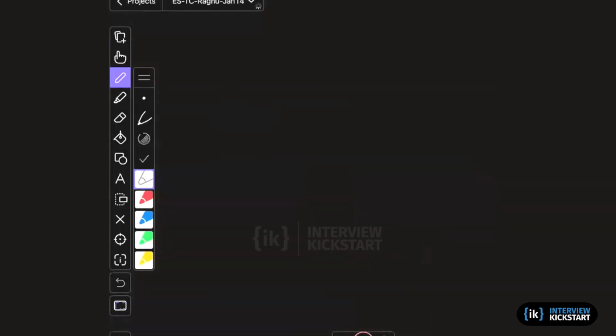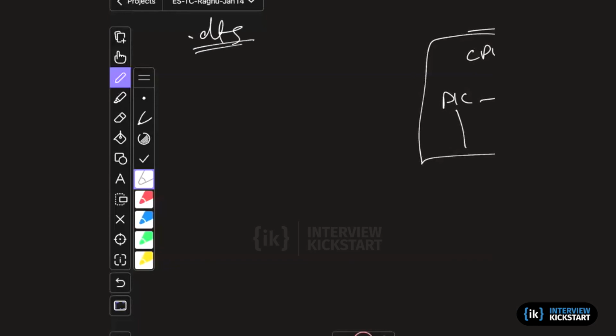Now, why is it called a tree? We talked about this platform having CPUs and then having I2C. You may have other hardware things. For example, the interrupt controller may connect to many of these devices. So basically, a .dts file will have a node per hardware unit. A unit here may be the PIC, I2C, etc. And then somehow you have to say how they are interconnected. So there is basically a pointer kind of thing, a reference or whatever.